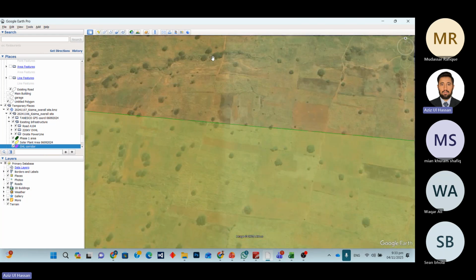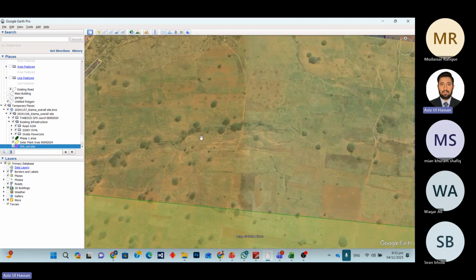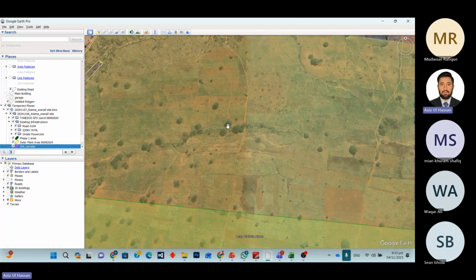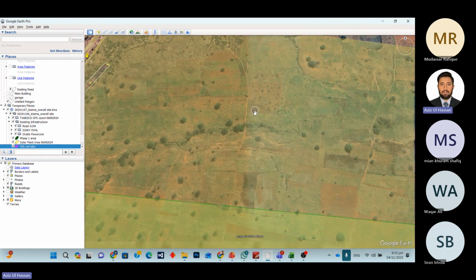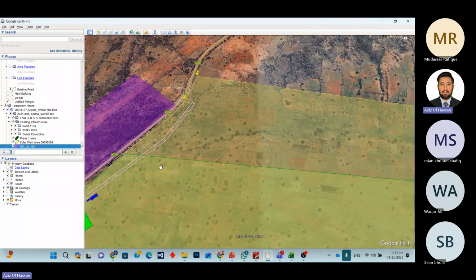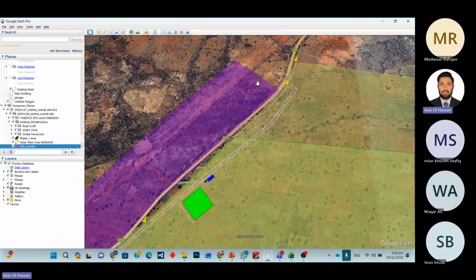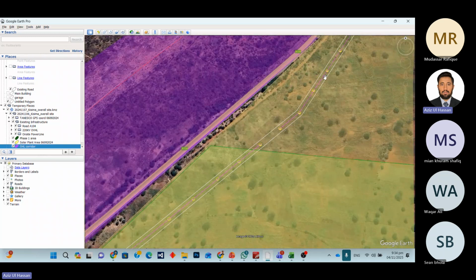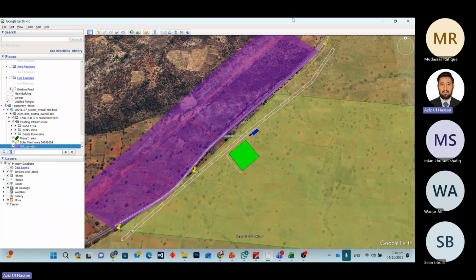So we have to mark the area of these trees, and also their shadow, to skip these locations for the PV module installation. So these are called the no-go areas. Like they have marked the transmission line. We have to skip this area and leave empty space around the transmission line for the passing, for the tower locations. We can't install the PV module in that location.